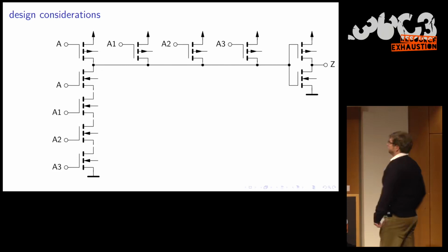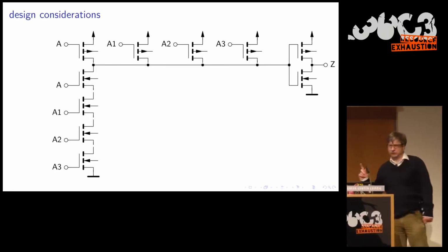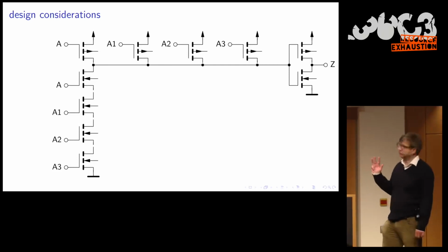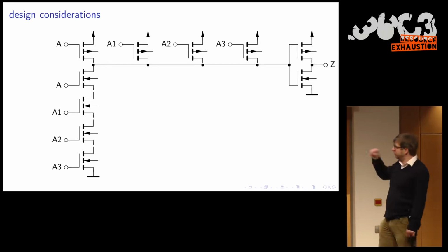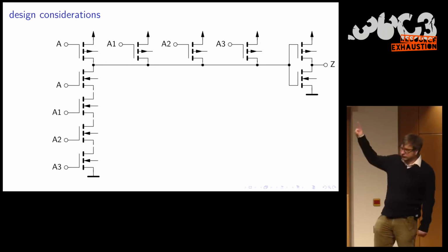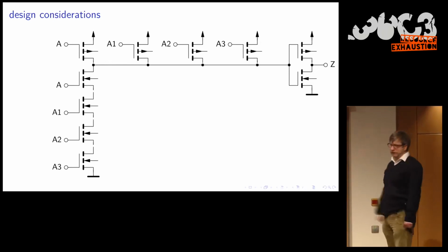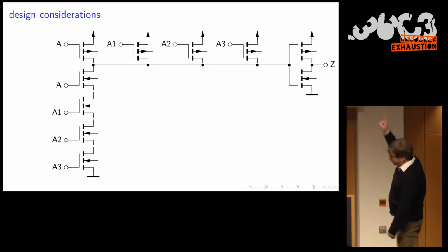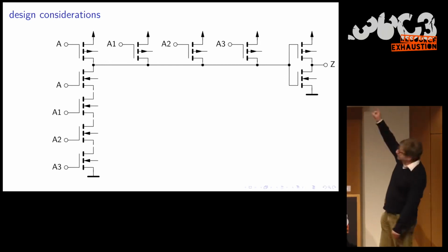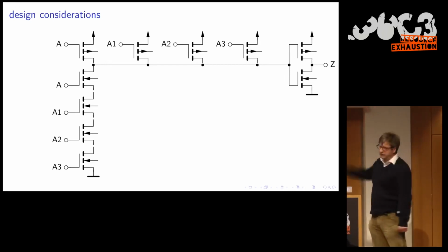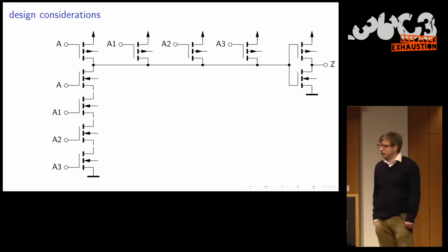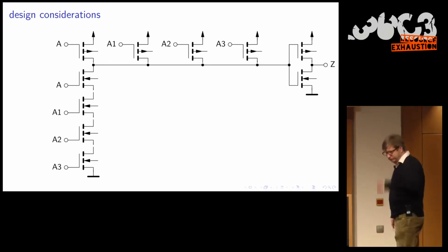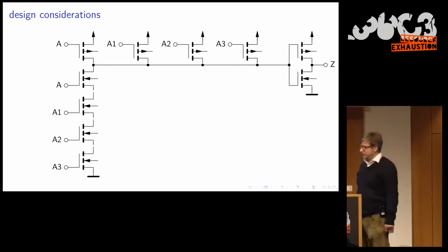So I have to explain something about this. How far can you go with these complex gates? This is an example for a NAND with 4 inputs. I don't know if you remember the AND from before. So here down below are the transistors in serial, and at the top you have the parallel. It's an AND, so I overlooked the buffer at the end. There's a small inverter at the end. So it inverts it, so I have an AND and not an AND.